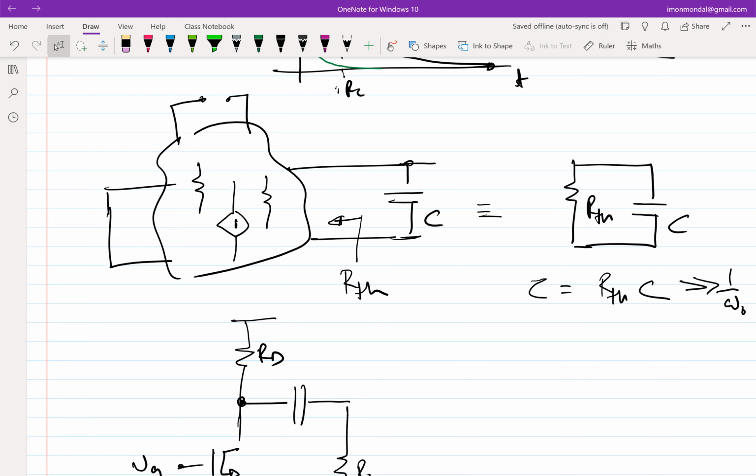Right? So I extract that information that, okay, very crudely speaking, if the time constant RC is very high, I can say that the capacitor inside is holding on to its charge, and if the time constant is low, the capacitor is discharging its charge easily. That is with respect to what you are saying, and it is right. That is with respect to applying a step input, right? Or if you are initially charging the capacitor and trying to see how fast it's discharging. Perfect.